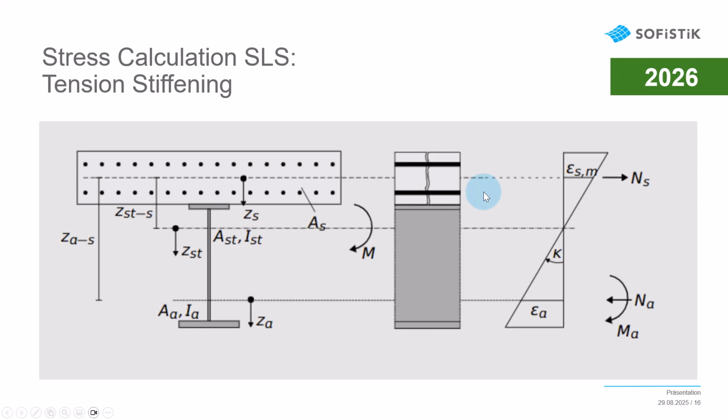Stiffness attracts loads, therefore the forces and reinforcement stresses in the slab of a composite girder are higher than those calculated using the pure cracked composite section, where only structural steel and reinforcement are considered as active.